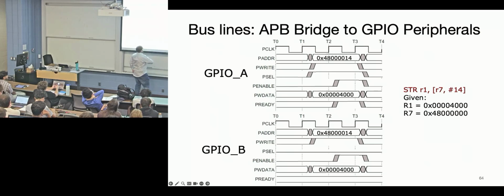So here, it doesn't even matter. This is P ready up there. P ready showing the bus, or the controller, does not care if it's high or low. This is the only time it cares, and it happens to be high. It is stating here that on the next rising clock edge, it is ready to do the thing. It does the thing, and then it gets deasserted, or it does not care. Does that answer your question?